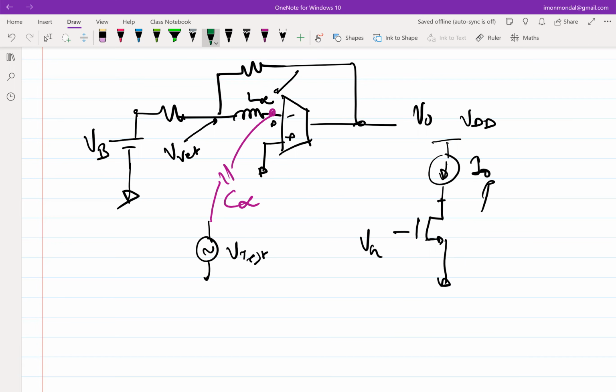So what you have here is essentially a PN junction diode, right? You have multiple PN junction diodes here. There is this junction and there's a channel, and the channel is not existing because you don't have VG, right? So maybe the first thing that will happen is this voltage will go up, and this voltage will go up, and the reverse bias current through the diode will start increasing, and the diode will eventually break. And that's what might happen, right? So this current might go through that. But if the reverse diode voltage required to break down that diode is very high, then before that, maybe I0 will shut off. So it now depends on which second order effect dominates.